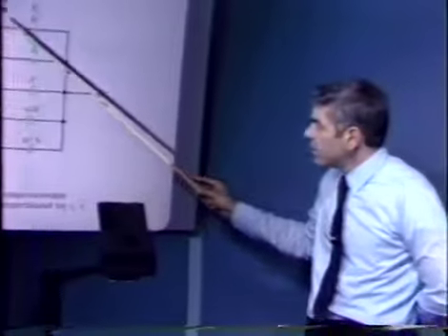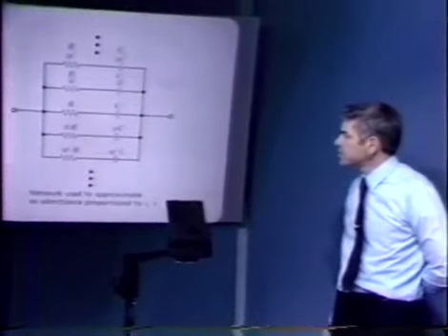When the transfer admittance is constant with frequency, you're approaching 0 degrees of phase shift. And in general, just as the roll-off of that network ripples, so does the phase. And you can control the amount of ripple really by the closeness of spacing of pole and zero pairs, or equivalently by the choice of the quantity alpha in this network. Well, it turns out that if you use only 1 pole and 1 zero per decade, you get a very, very good approximation to 45 degrees of phase shift associated with the transfer admittance.